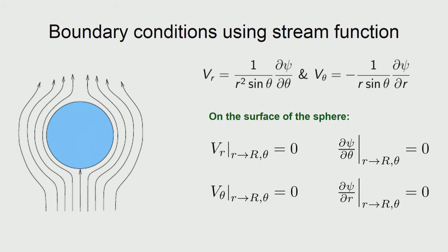the continuity equation, then the equation would be satisfied. Okay, so, now we look at the boundary conditions. The boundary conditions are to be written as follows. The solid sphere is impenetrable and it is smooth with the no slip condition on top, which means that the velocity components are 0. Okay. So, the Vr, that is the radial velocity on the surface of the sphere, is 0, and similarly the theta component also will be 0, and this is basically the no slip condition and impenetrable wall condition.